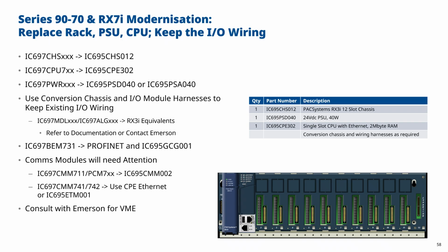If it's any other sort of device, then embedded IPC is probably pretty straightforward. We would move to one of our new next generation IPCs running independently, but you'd need to check what the application is. Chances are if it's an old VME module, it may be running some legacy operating system. It might be an old version of Windows, it might be VxWorks, it might be QNX, it might be, who knows, because VME is very old now.